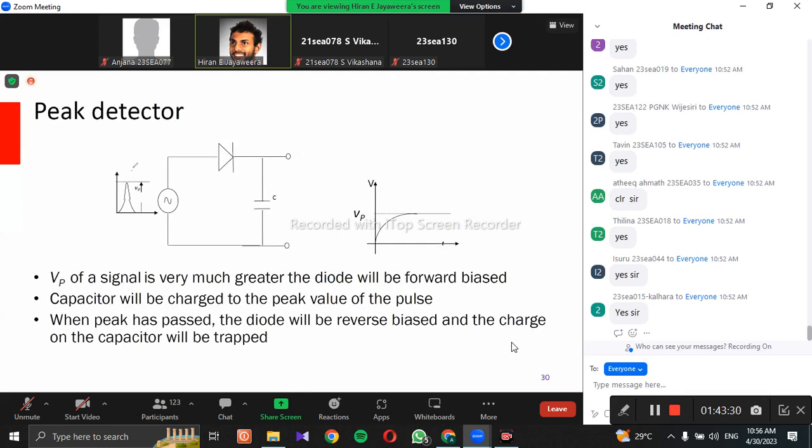Now, what you have here as the input is some sort of signal. It's a voltage that varies over time. But let's say you are taking some measurement and you need to detect what the peak voltage is in the system. We don't know. Probably it's some voltage coming from a temperature sensor. So we just keep on measuring it, but you need to record what the maximum temperature is in this system. For that, you can use this circuit.